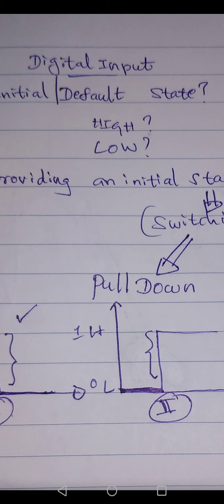Maybe you can connect the pin to ground, then it will become low. Maybe you can connect a 5 volt pin, then it will become high. But in case you don't connect anything to the particular pin and you digitalRead the pin value, what is the pin's state, high or low? What do you think the default state is? So there's a problem, we don't know.